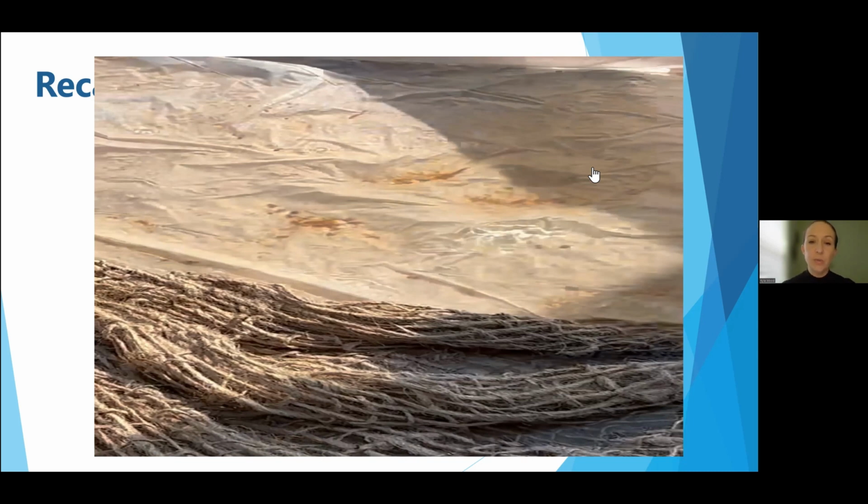Eventually, when you need to dispose of those, again, it's not hazardous, so if it's possible, you can leave them in place because it's biodegradable. You can also dispose of them however you would otherwise dispose of those sediment control devices.